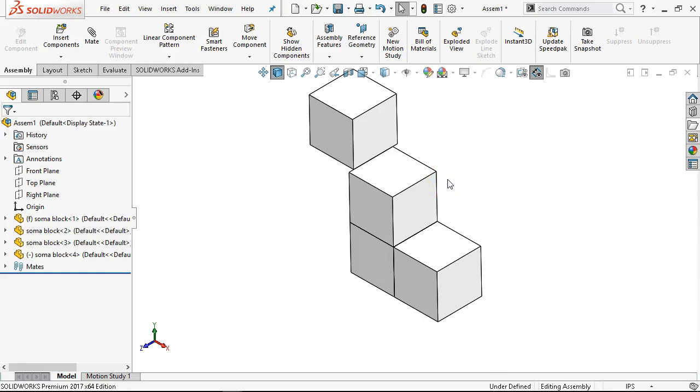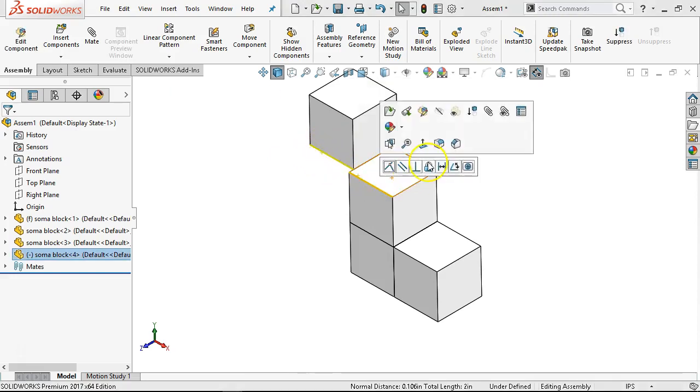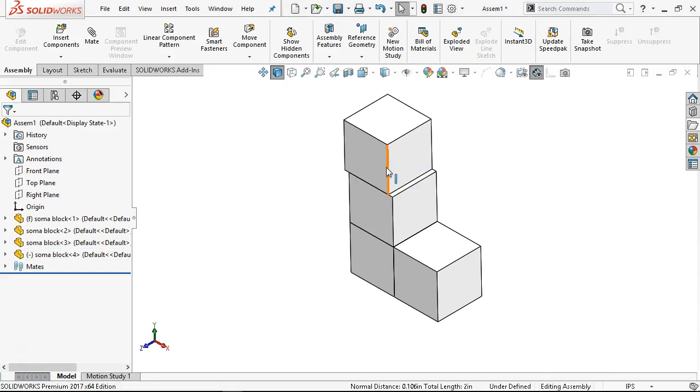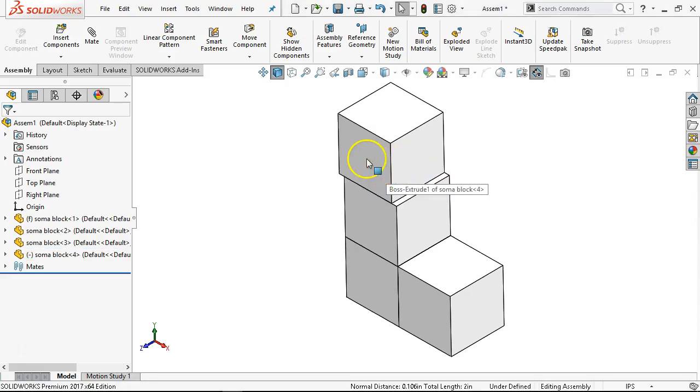All right, so we said plane to plane, plane to face, face to face as my hierarchy. Lesser choices are going to be edge to face, edge to edge, point to all of the above, point to point. And there are going to be some reasons why. So if I go edge to edge and make those coincident, I'm going to bypass going into the Mate PropertyManager, and it will go right edge to edge.